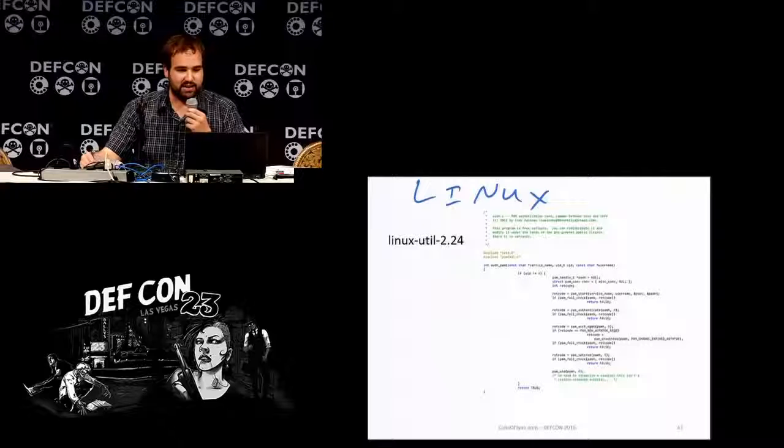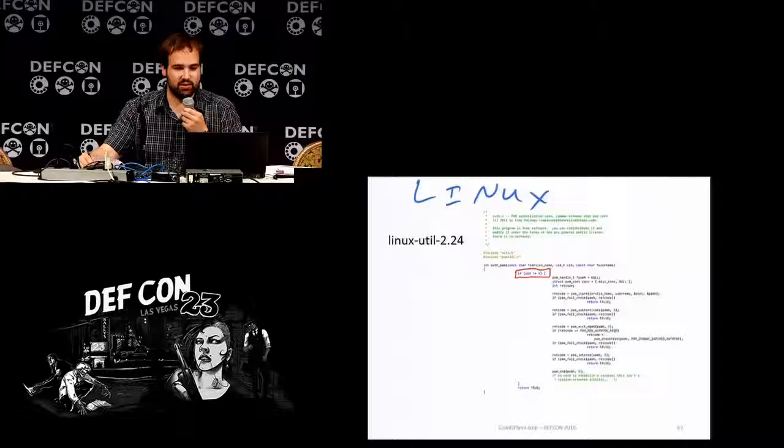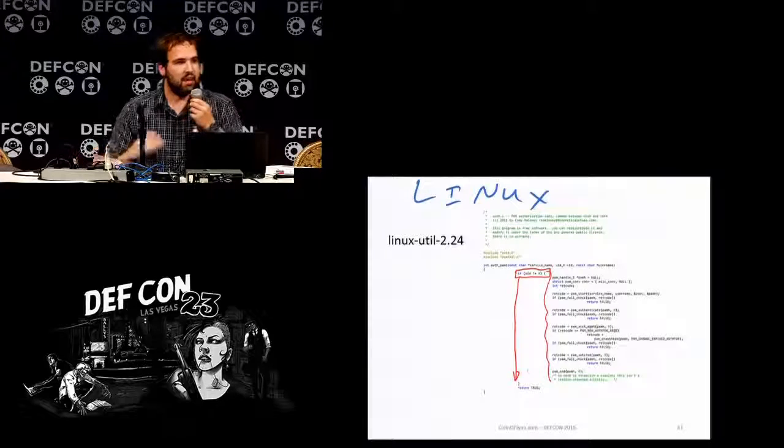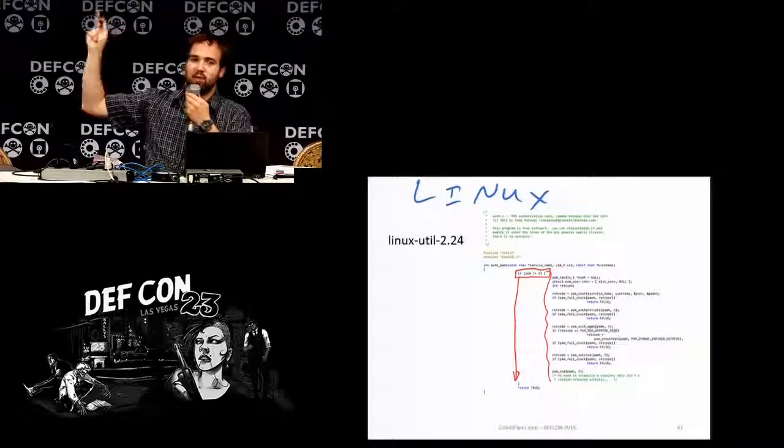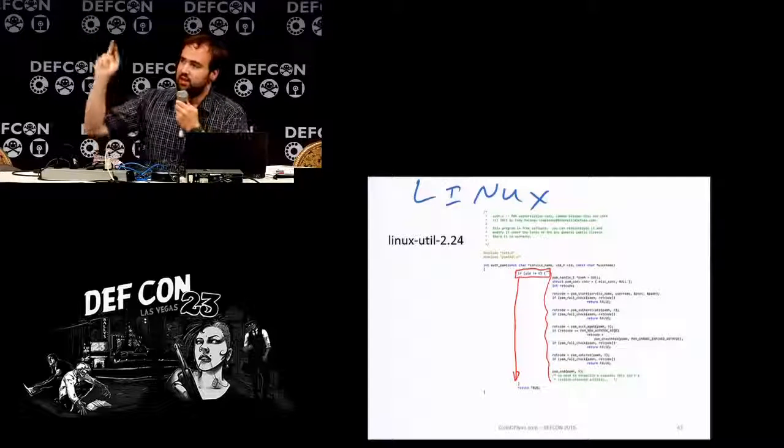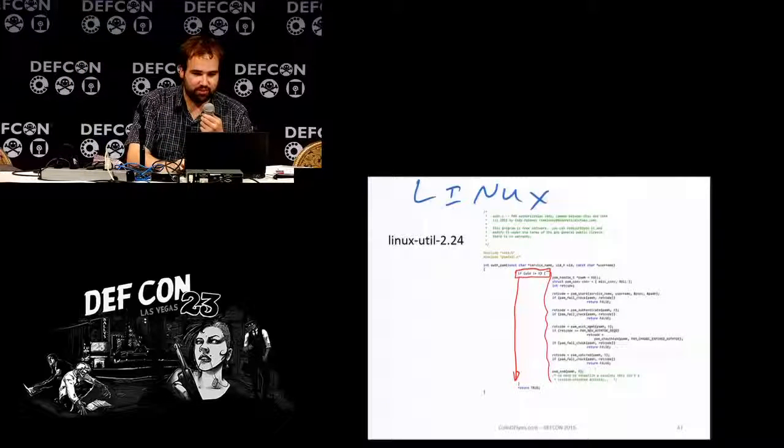Really what we're looking at is that when you look at the code, there are all sorts of lines like this. This is you logging into Linux. There's some point that says, hey, if your user ID is not equal to 0, check the various authentication methods. If it is equal to 0, just skip out. And with glitching, what we want to do is actually screw up that comparison. We want to make the hardware device perform the wrong operation there.